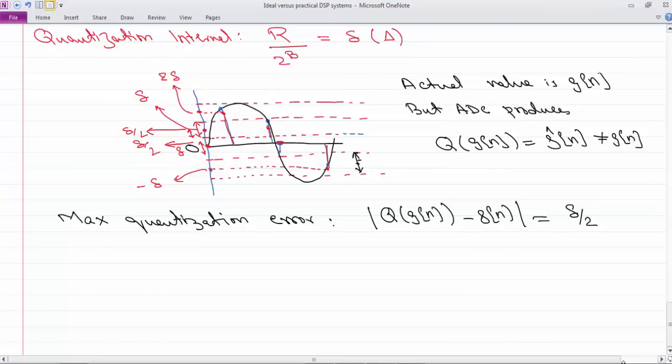What you measure is not exactly what the signal had because you had to quantize it to a certain number of values. But this quantization error can, of course, be reduced. So how do you reduce it? The quantization error is given by delta over 2, which is a function of your quantization interval.